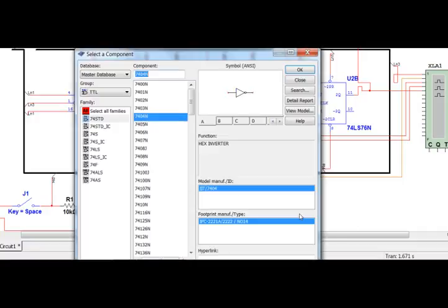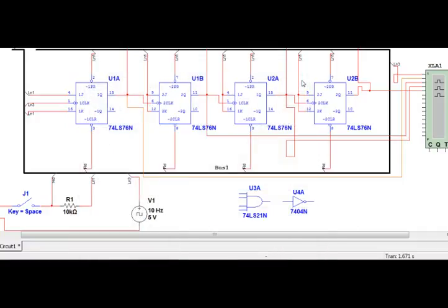All right, that's good. So how are we going to decode a 10? A 10. So this is 8, and 0, 1. I put that guy in the wrong spot, didn't I? I want him to be on the Q naught, so this is in the wrong place. We want him to be over there. So I'm decoding a 1, 0, 1, 0, which is a 10.